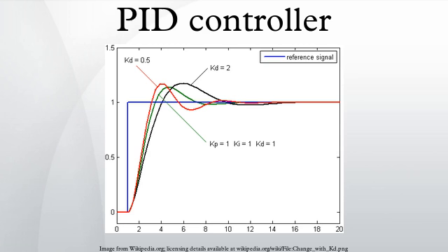The PID controller primarily has to compensate whatever difference or error remains between the set point and the system response to the open-loop control. Since the feed-forward output is not affected by the process feedback, it can never cause the control system to oscillate, thus improving the system response without affecting stability. Feed-forward can be based on the set point and on extra measured disturbances.